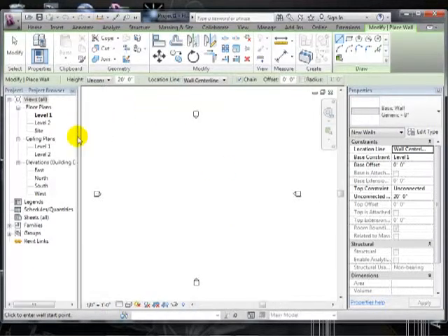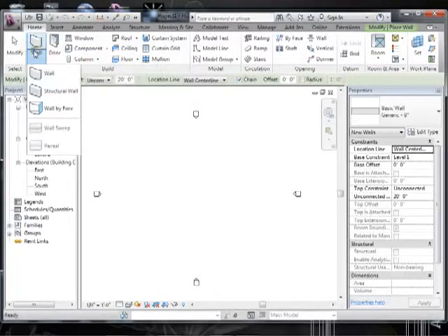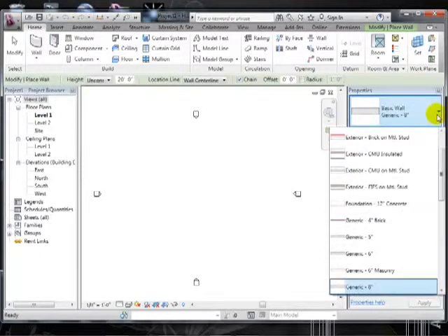Now, when we're actually working with walls and we go under the Home tab and choose either the Wall tool or the Floor tool, you see over here in the Properties palette, up at the top, there's this type selector, and the type will show you the different types of walls that are available. Most people will start just by drawing generic walls, things that just have some generic material but not a whole lot of layering to it.